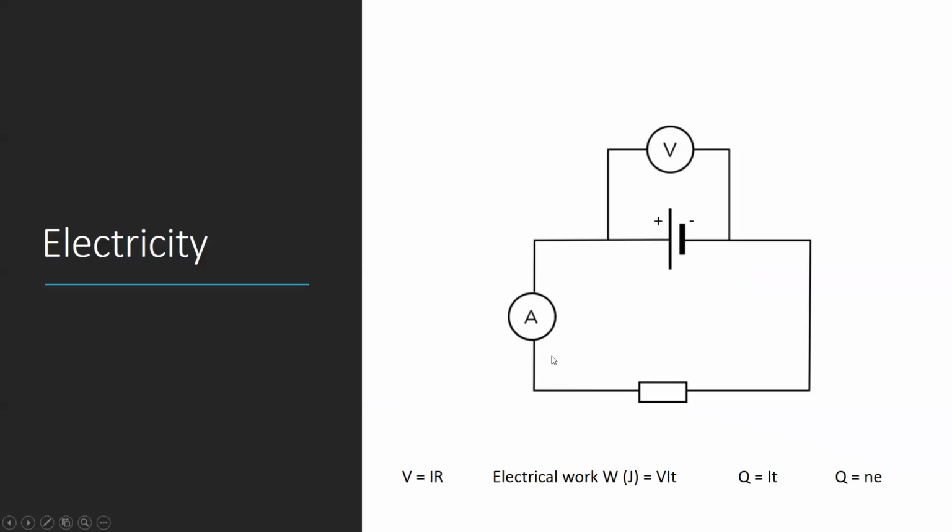Now, this brings us on to some equations. First, the voltage is related to the current and the resistance by V equals IR. This is obvious if you think of the resistance as blocking the flow of electrons that is driven by the voltage. Now, resistance can actually be necessary in circuits. It's what creates heat as electrons bump into other atoms. For example, how filament bulbs work is the resistance in the filament creates heat, and when the filament gets to a particular temperature, it begins to emit light.